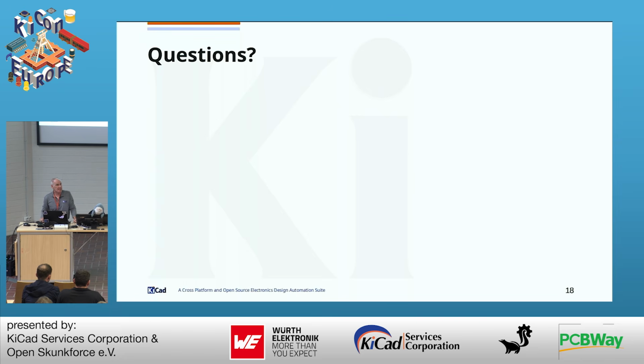Yes. If you delete the symbol, all three of them will go away. But if you delete a variant, all the footprints associated with that variant will go away. Because remember, when you do an update PCB from schematic, everything that's gone from the schematic goes away. Now, you can disable that. I think there's an option that says remove footprints that aren't in the schematic. You can leave them there. But eventually, when you sync again, you're going to have to reconcile the fact that your board doesn't match what your schematic is telling you it should be. So either you have to maintain that outside of the schematic, which is always risky.